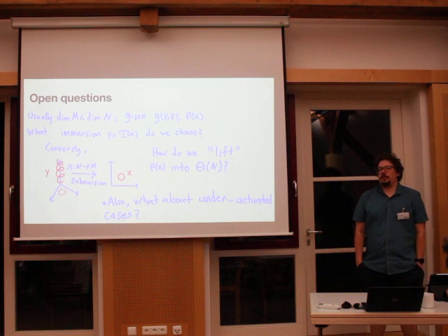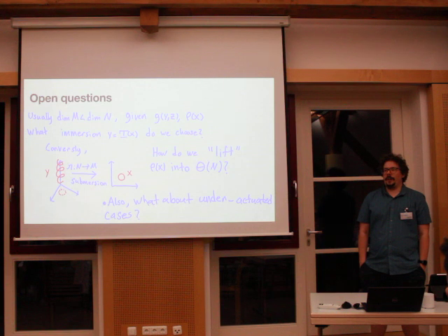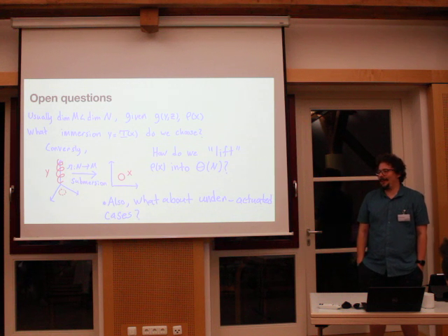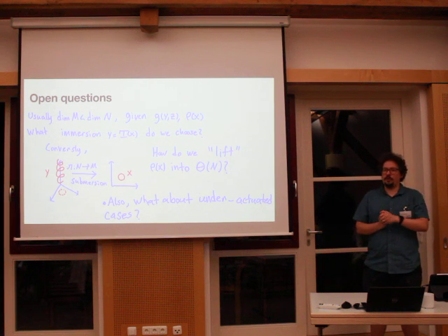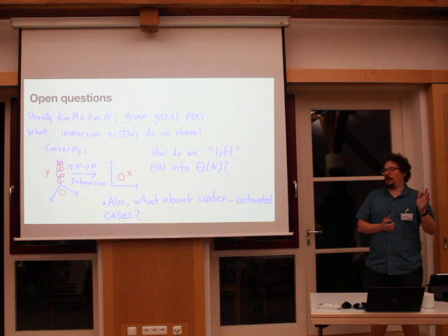Yeah, so it's a challenge, right? Once you have integer or binary variables, now it's less straightforward to solve because you're not going to just be able to use techniques from smooth optimization. It's an NP-hard problem at that point, and you maybe need to do branch and bound, or you have to decide before you design your robot, here's the general schema that I'm going to consider in my class of design. So restricting it to choosing a priori what type of actuator, what type of linkages, and where the compliance goes.